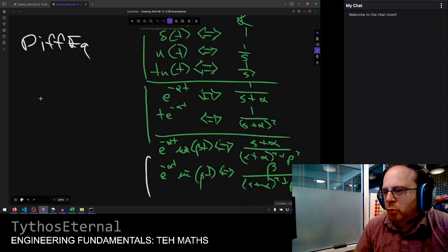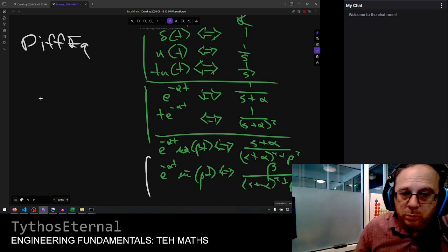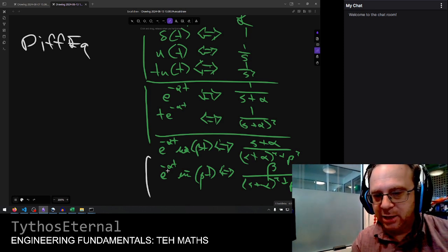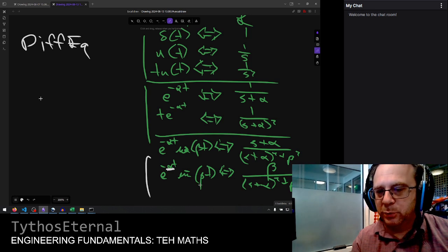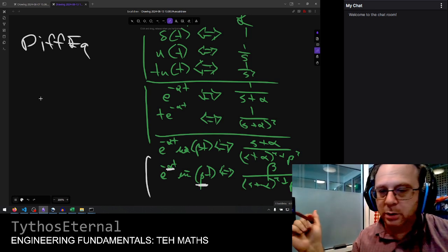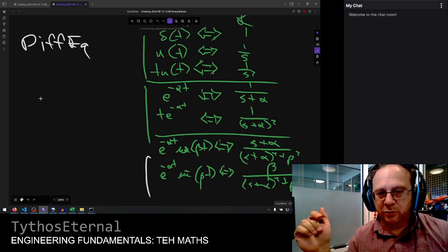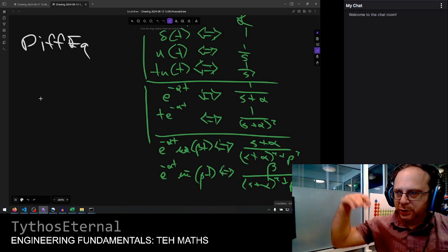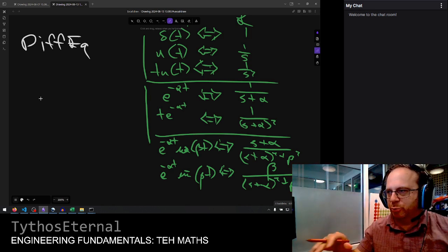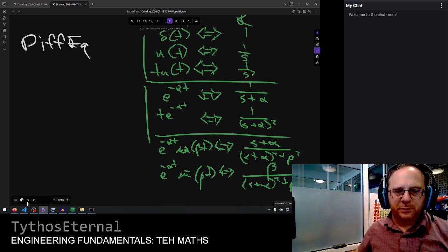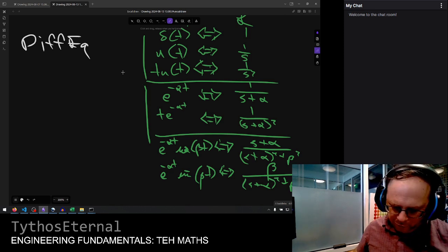Much like we would do with a Fourier transform. So we're then able to characterize the system in terms of what the decay rate is and what the frequency of the oscillation is, right? And that lets us characterize things like the settling time for a particular response, or the natural frequency, understanding how energy is moving through the system, which lets us predict a lot of very useful things about the dynamics of the system itself.